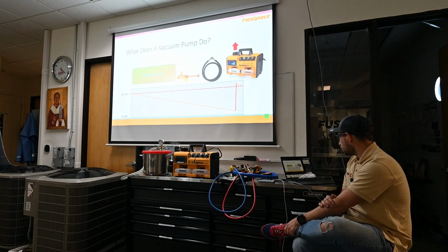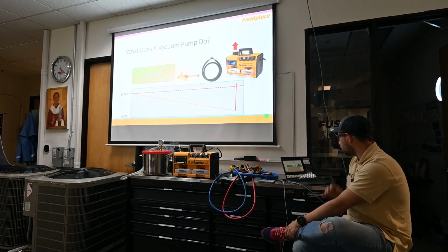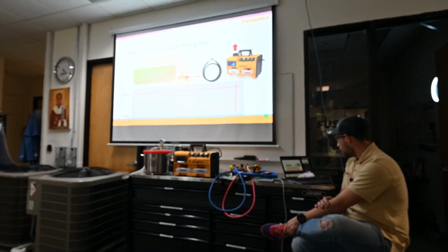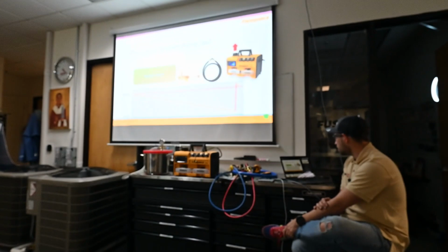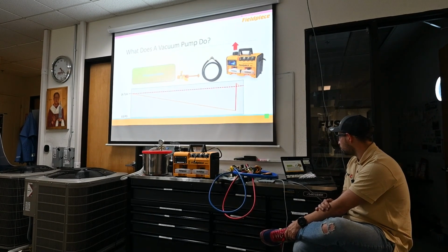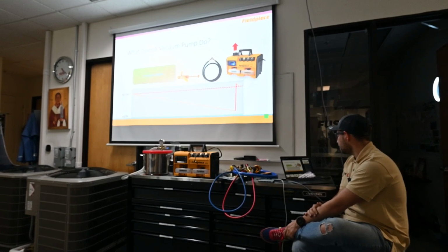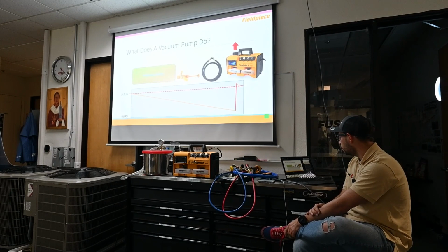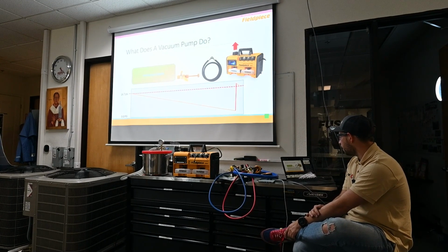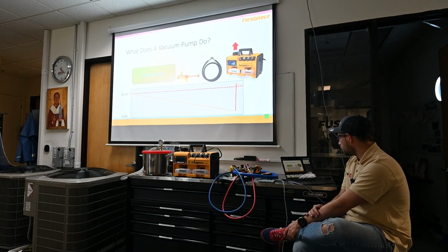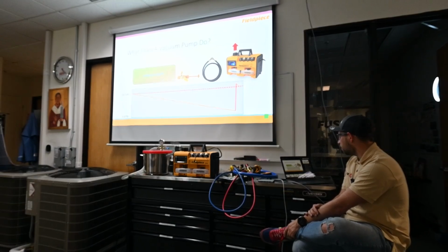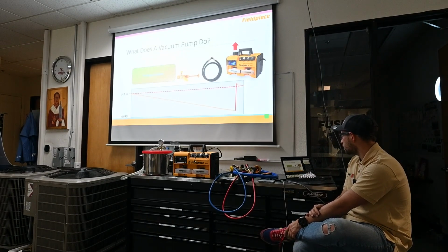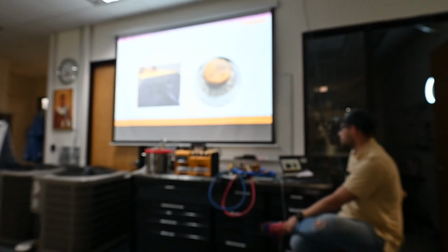As the pump runs, the hole keeps getting deeper as the molecules from the sealed systems are removed. As the pump ejects molecules out, the system's pressure gets lower. The deeper the hole gets, the lower the pressure differential between the systems and the pump becomes. As the pressure difference decreases, the number of molecules available to eject from the pump decreases, so the process slows down. Gas ballast.